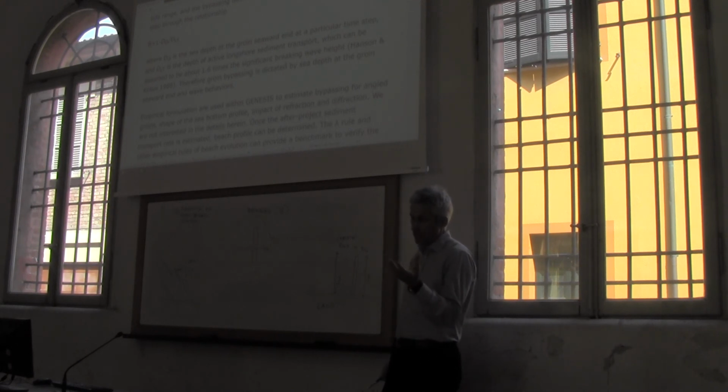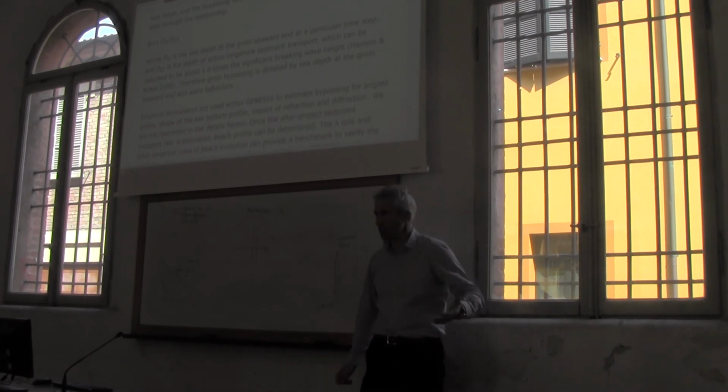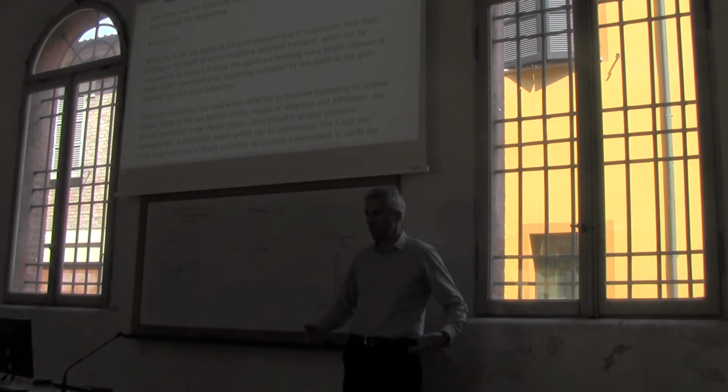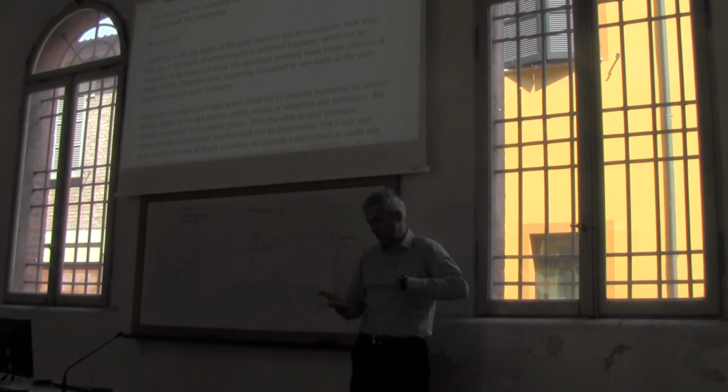I give you an example. If you go on the Adriatic Sea close by here, and you have sand for about 1 kilometer, you can walk into the sea for hundreds of meters, and you still feel that there is sand beneath your feet, because it's very gently sloped. We cannot build groins that go into the sea for hundreds of meters. Usually we build groins that go into the sea for some 30 meters. Still, we observe that the bypassing is limited.